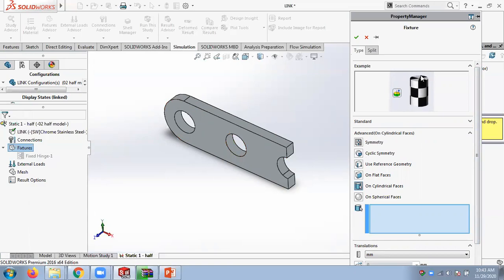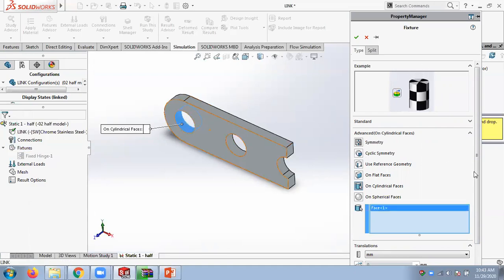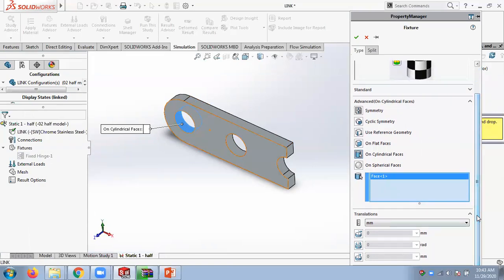We have to stop the axial movement. We have to stop the radial movements. We can allow circumferential. When you click on this, we have to give those conditions. So you may understand it now clearly. We cannot allow radial movements, that is, we cannot allow this to be expanded.